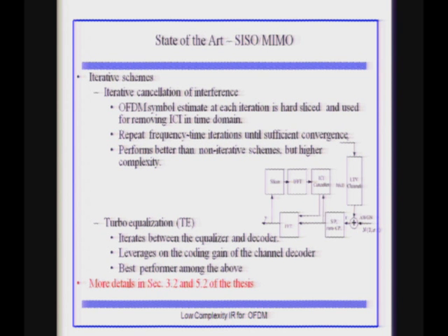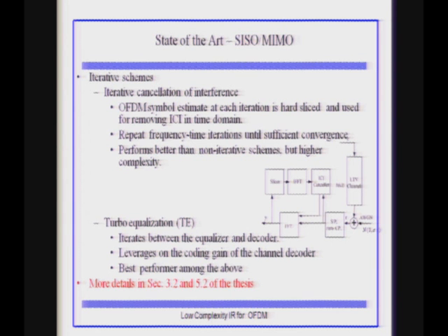Whereas the major ones, which are nowadays very popular, are the turbo equalization based schemes, where you leverage the coding gain of the channel decoder, the coding gain of the code that you use, and that is the best performer among all the three we've seen. And more on the available literature is in different chapters of the thesis.